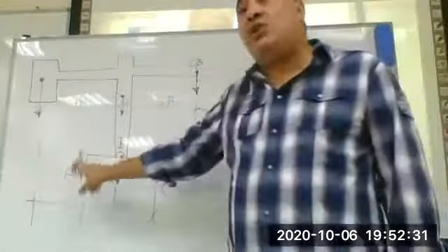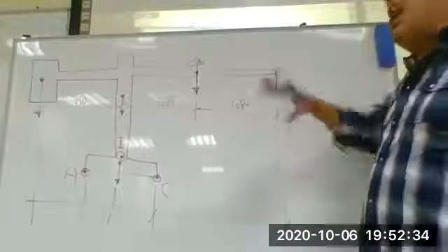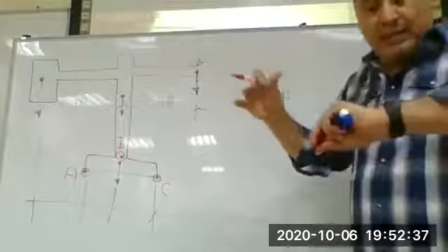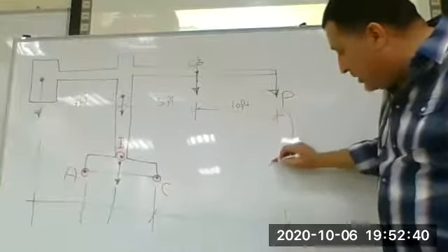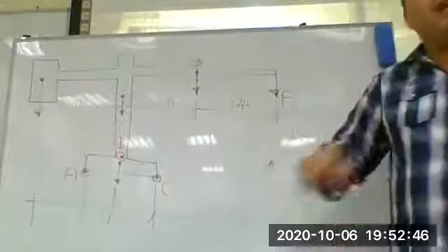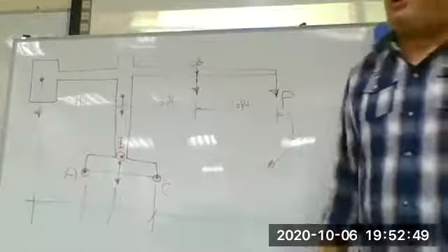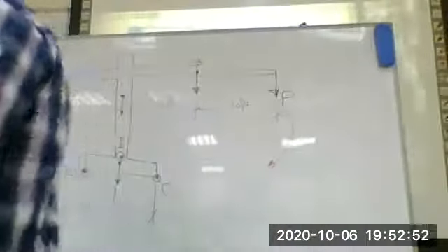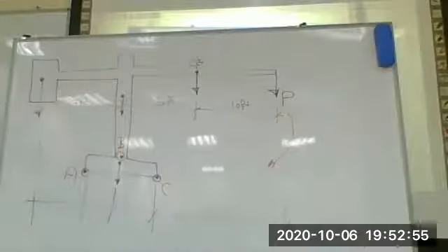This system can overturn, can it hit B? Yeah, this system gives too much, more than the limit. The load gives moment in this direction. Where is the nearest point for this load? C. Where are you overturning? Here, around C. It cannot be B because B is a rigid condition. It cannot be overturning because B is like the rigid condition where we have the action load in this foundation. From this action load, we will calculate how much is fixed in this foundation, the size of the foundation.